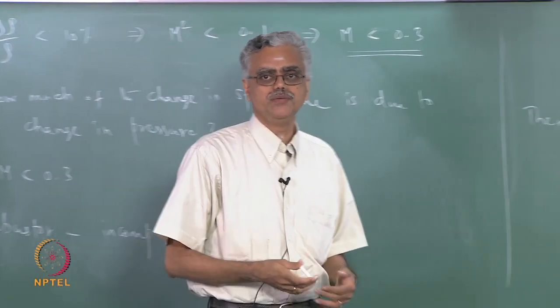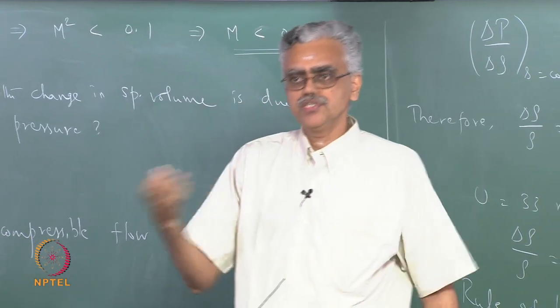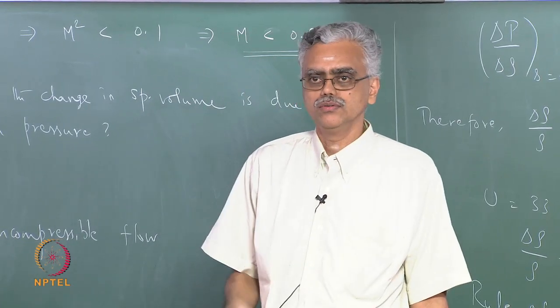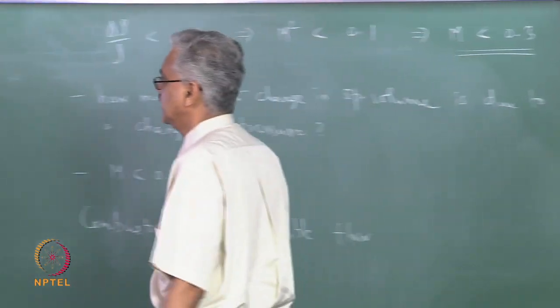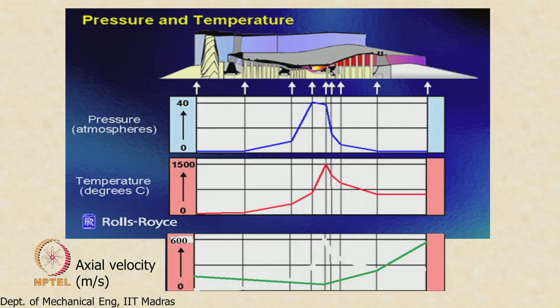The flow itself may be moving at high speed, but the temperatures are very high, so Mach numbers are also low. That also tells us indirectly that we do not have a problem with the combustor. You can see that the velocities are here.